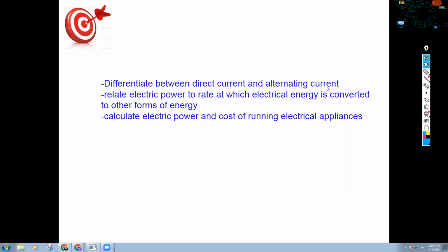We're going to take the last step before we get into circuitry and talk about the last piece of the puzzle. We've talked about voltage, the pressure behind, and the potential difference. We've talked about the flow rate, how many coulombs per second are passing by, thinking of that as gallons per minute if you equated that to our analogy of water. And then resistance, talking about how much internal friction those charges are going to face as they go through, putting it all together with Ohm's law, and that's V equals IR.